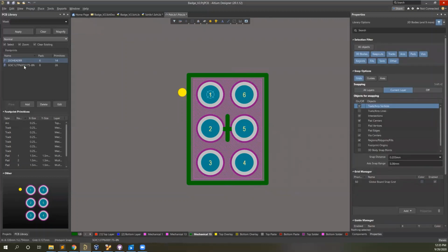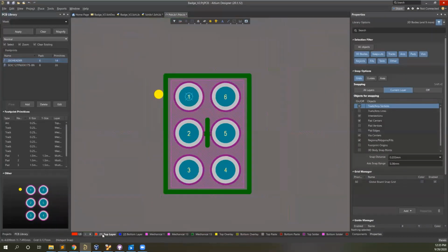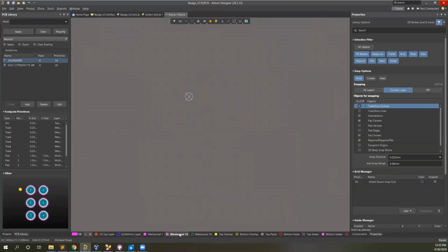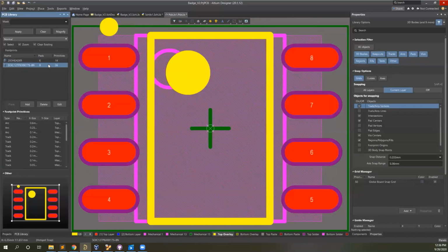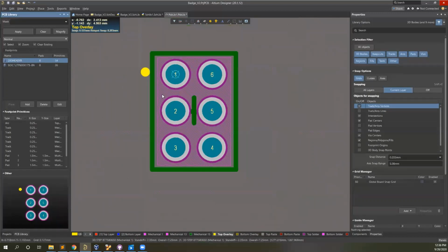And yeah, so you can compare this to this component, and you might be wondering why there's no red for the top layer. You'll see these are through hole parts. They're on both the top and the bottom layer, so it's not red because they're just plated through holes. You can slide through all these different things, and you can see that it's pretty similar. We can also apply a solder paste to it if you wanted, or solder layer. But this is pretty sufficient for this part.